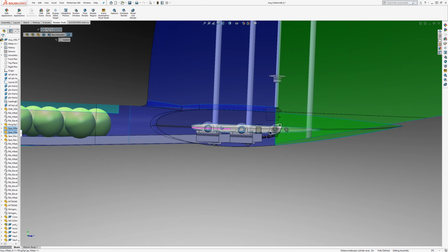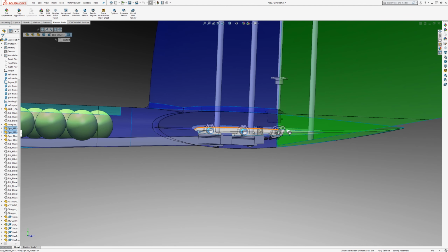And if the lift of the HStab is in front of the forward spar, then we're going to have one spar reacting a lot in one direction and the other spar reacting a bit in the opposite direction to balance that torque.